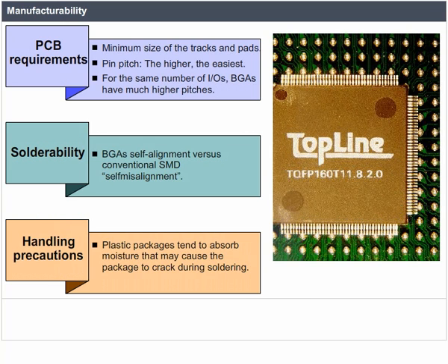Handling precautions. Plastic packages tend to absorb moisture that may cause the package to crack during soldering. Bottom line, always keep in contact with your PCB manufacturing and mounting partner.